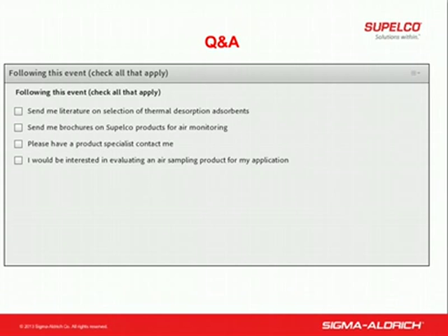Okay, and we have another question here. Can glass tubes be used for passive sampling? The answer is no, and the reason is there wasn't any development work done on those. For example, the glass frit doesn't have the consistent hole sizes that we need to control the flow, compared to the stainless steel tube that has a stainless steel mesh screen that's very precise.